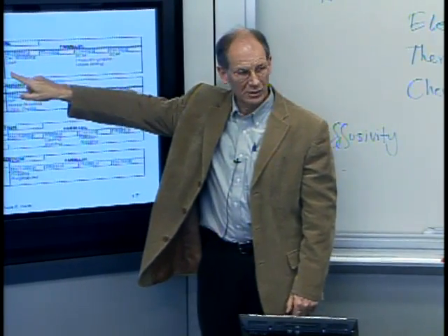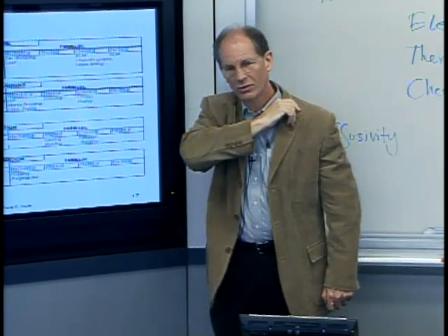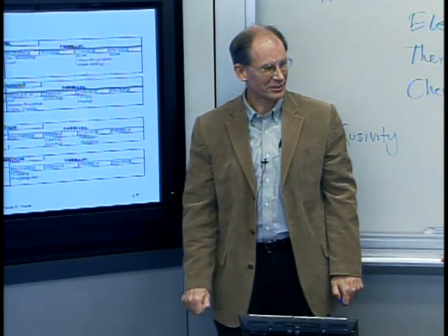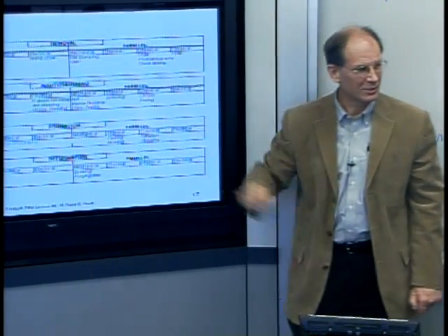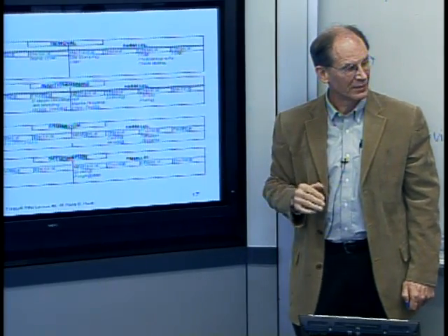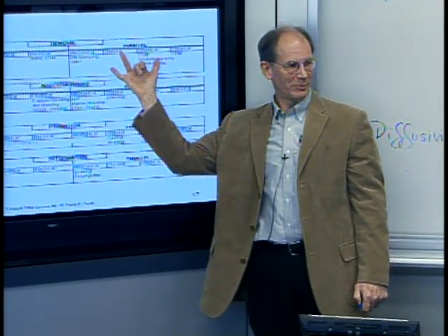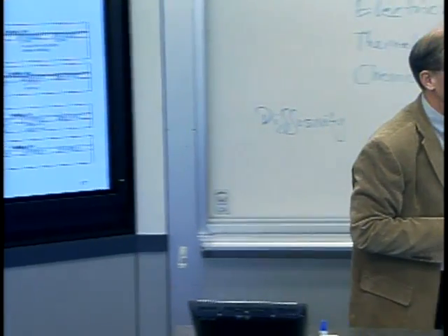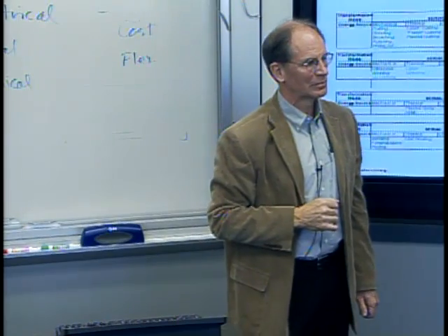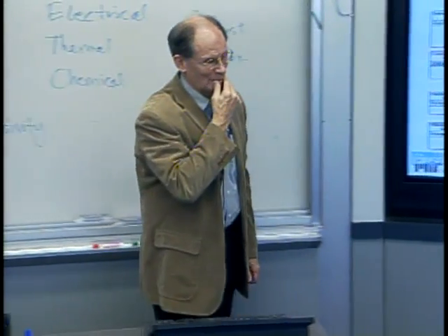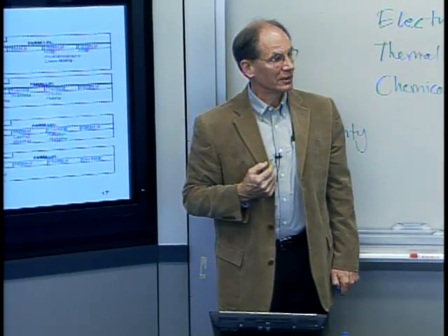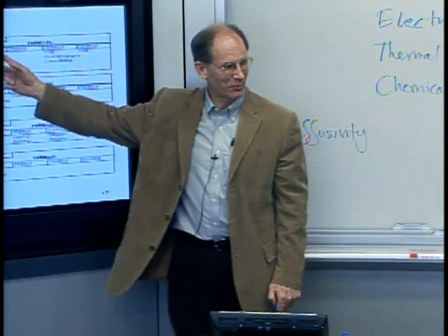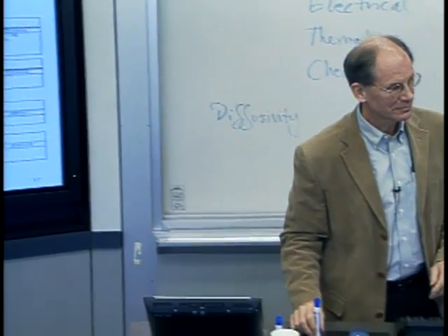I think Duane has already talked about chemical mechanical polishing, which I'm told by the experts in the field is really mechanical polishing, right? So if we take the C off of there, then CMP is a mechanical parallel process. If it's a chemical mechanical process, then I guess it has to show up in both of them. Which is it? Is it both? The chemistry softens the surface enough that the mechanical abrasion can occur. So you have that both. Okay. But the chemical by itself would not remove any material. Okay. Chemically assisted mechanical processing. And strangely enough, the abrasion by itself would not remove any material. Any at all.